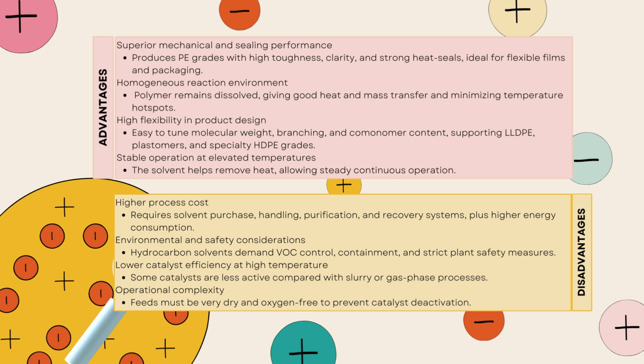So we go next to the disadvantages of solution polymerization. The first one is higher process cost, because it requires solvent purchase, handling, purification and also a recovery system. The second one is environmental and safety considerations. The third one is lower catalyst efficiency at high temperature. And the fourth one is operational complexity.